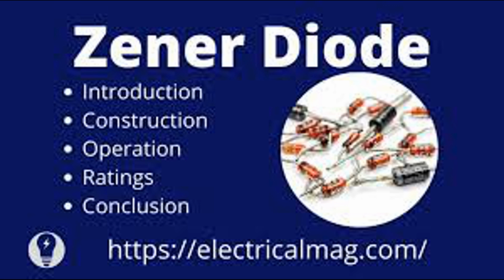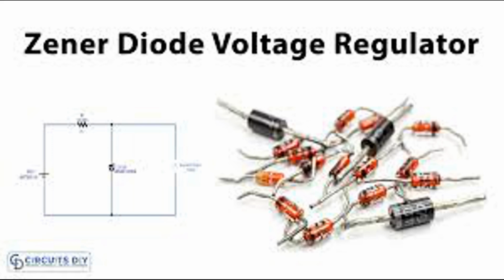Over-voltage protection. They safeguard electronic circuits from voltage spikes and surges by clamping the voltage to a safe level, protecting delicate components from damage. Signal clipping. In signal processing, Zener diodes are used to clip signals to specific voltage levels, preventing distortion and maintaining signal integrity. Voltage shifting and level shifting. They can shift voltage levels in logic circuits and other applications, facilitating compatibility between different voltage levels. Reference voltage. Zener diodes provide stable reference voltages for precision measurement and analog-to-digital conversion applications, ensuring accurate and reliable operation.